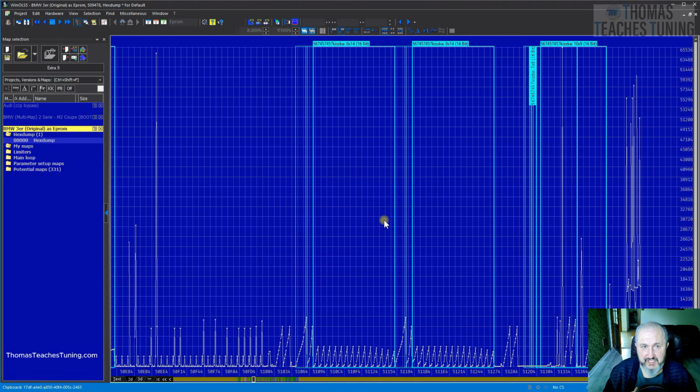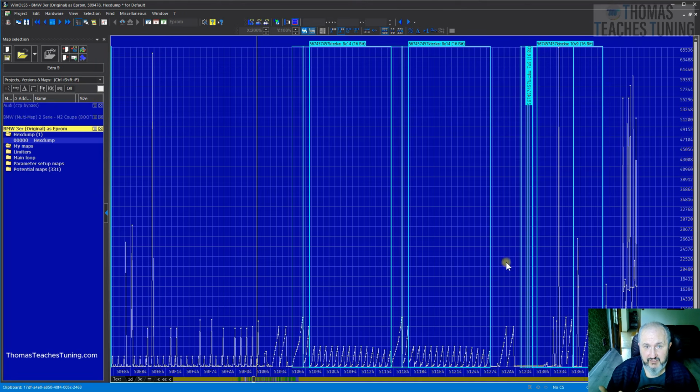What matters is that the maps follow the same sequence in ECUs of the same type. While there may be multiple sequences, the number is limited. For sure, limited. With older EDC17 ECUs, there is often one universal sequence, except for the Fiat Ducato. But all others follow the same sequence.